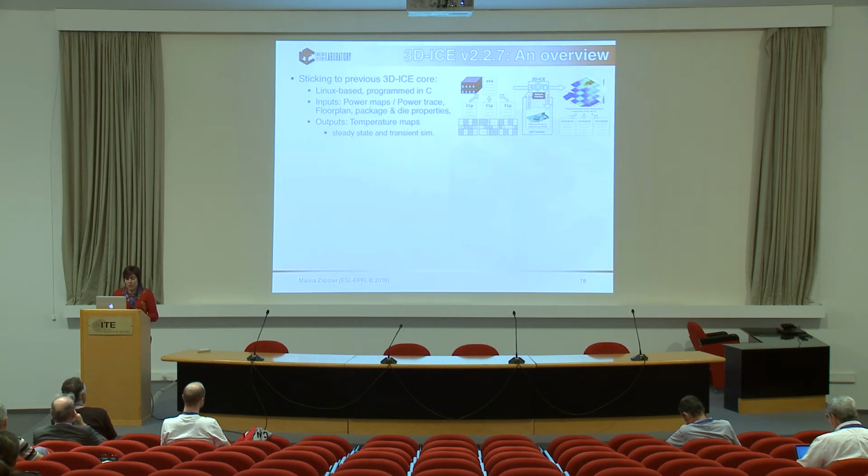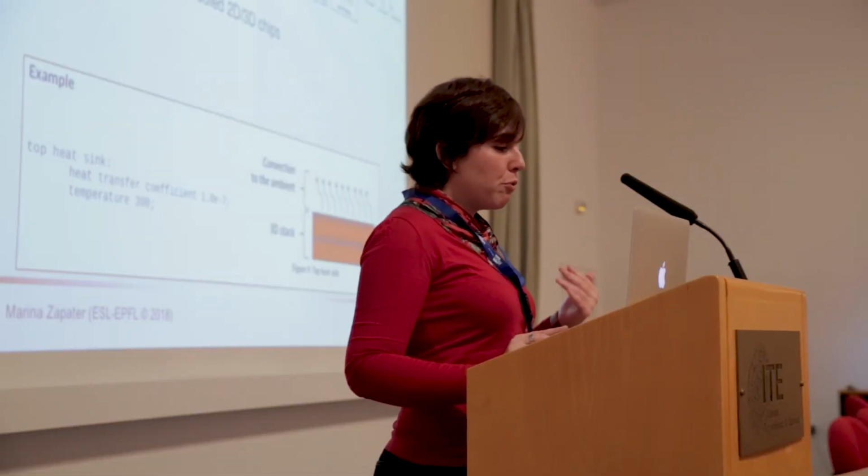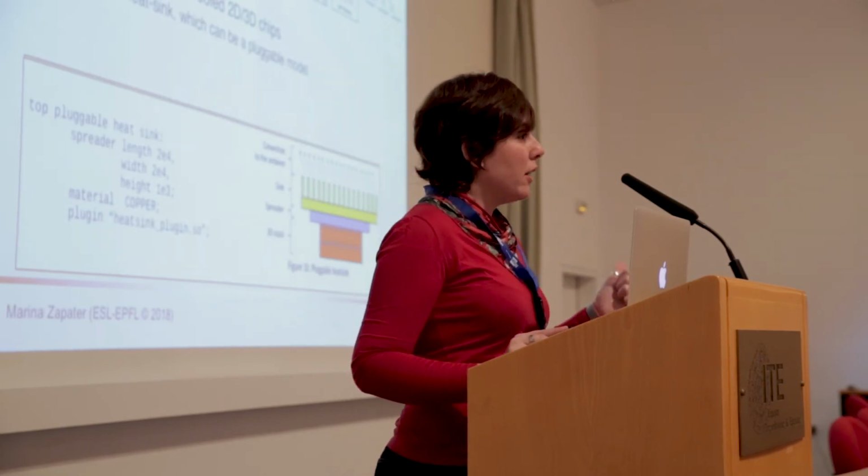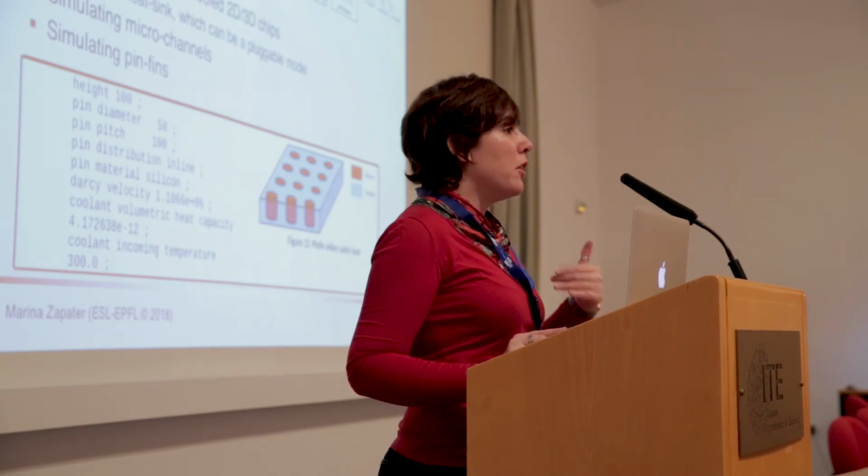So today, basically, we still have the same capabilities that we had before. 3D-ICE is programmed in C, and it works on Linux systems. You input power traces, and it gives you temperature maps, basically. Its main features are that you can simulate regular 2D or 3D chips. You can put a heatsink on top of that, which can be pluggable, so you can plug it in with any other model. You can simulate microchannels, and you can simulate pin fins.